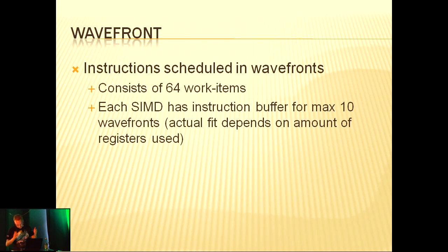We're basically operating on wavefronts, which is a very central topic here. Wavefronts consist of 64 work items. You can think of a single work item as a single vertex or a single pixel, for instance. Each SIMD has an instruction buffer for a maximum of 10 wavefronts.